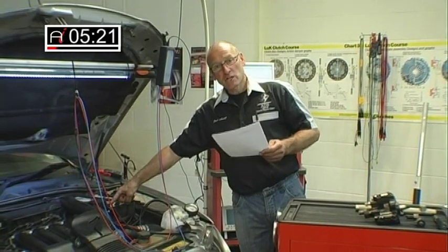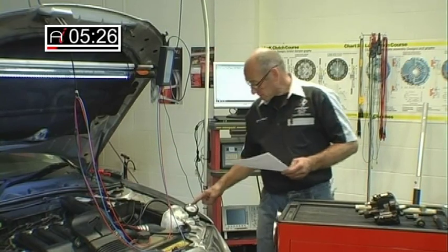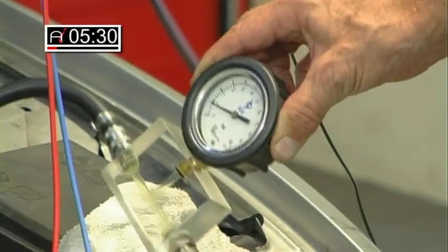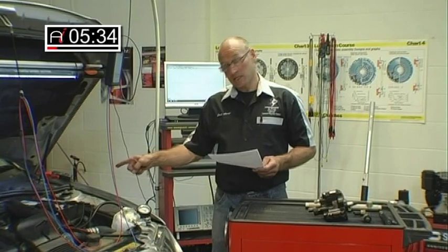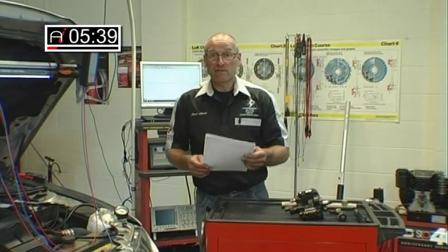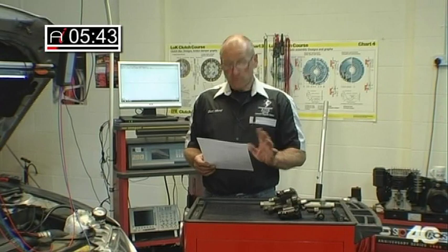Our view is the end product of priming is a hydraulic function, and the hydraulic function is pressure and flow. We go for the final function. I have at this moment in time no interest in that pressure sensor. I want to know what's happening hydraulically in the system. That's the first DTC. There's a DTC relating to the cooling fan, of which I have no interest with.